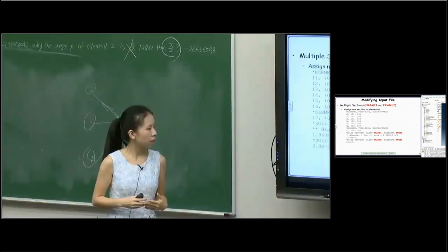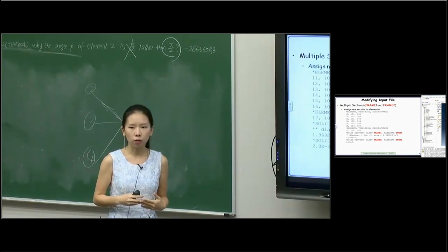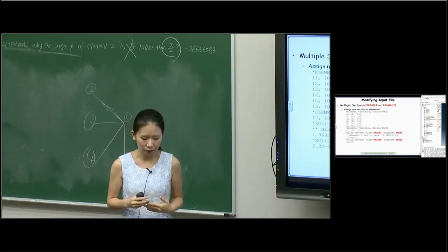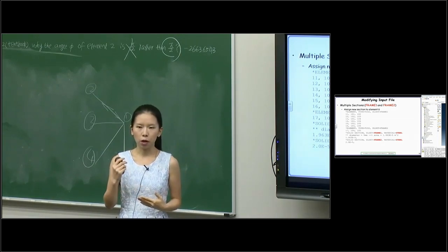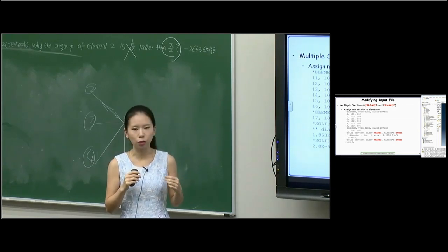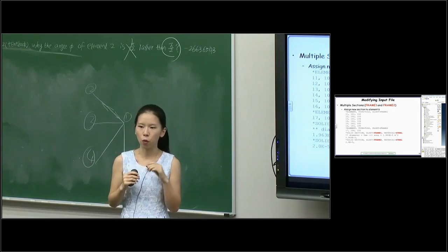And so today I will do a fully stress design. Fully stress design basically means that for a structure, when you apply load, it will show the stress. For the initial structure, I use the same cross-section area for all the truss.